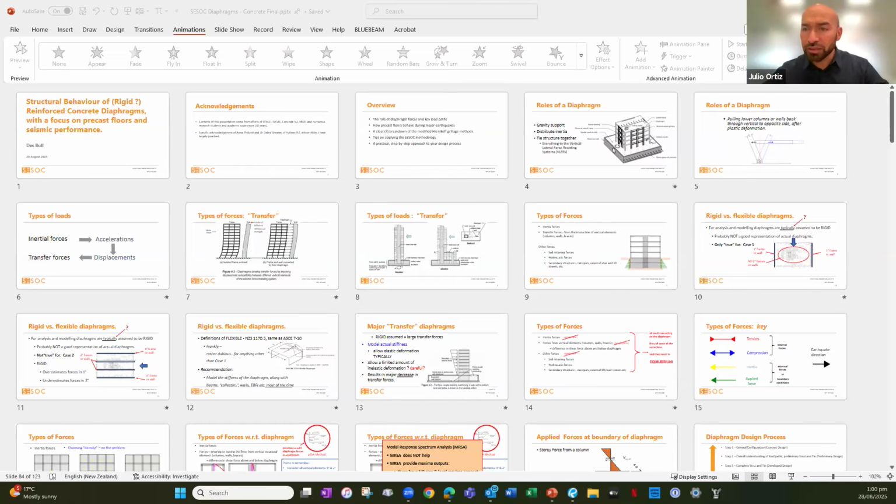That's great. Now, the pseudo-equivalent static analysis load accumulation at transverse diaphragms tends to become incredibly large. Is this real or just an accumulation of the simplified method? Any suggestion how to deal with it? Do me a favor, say that one again.